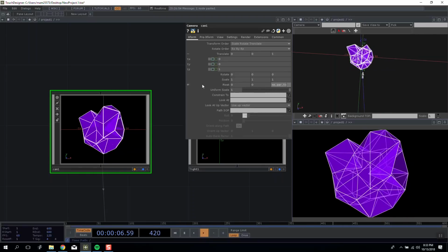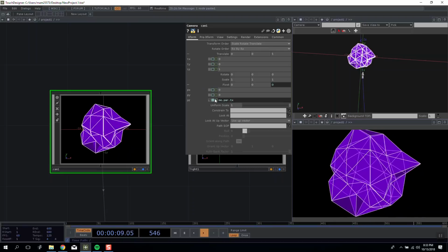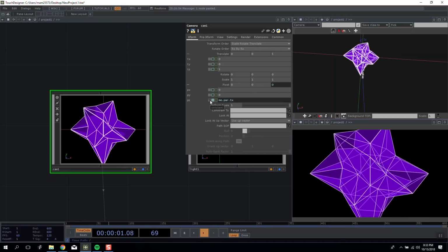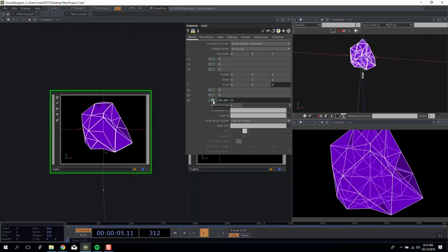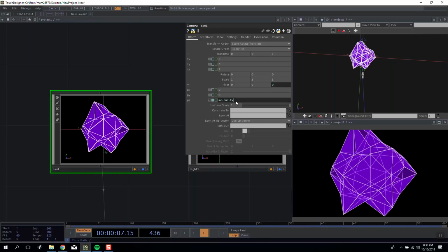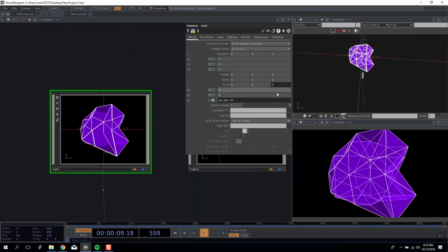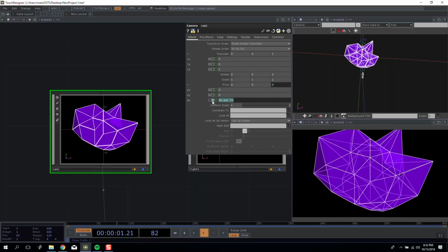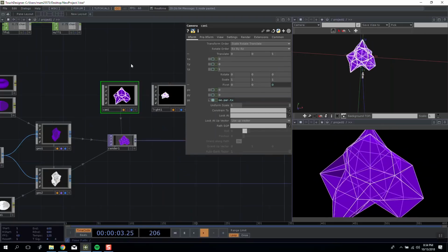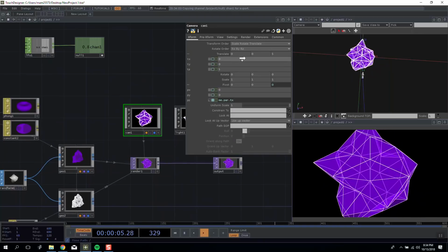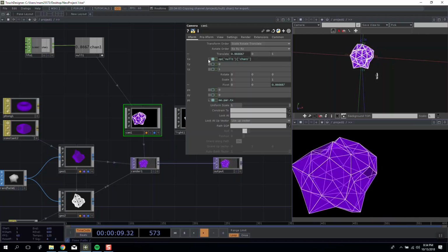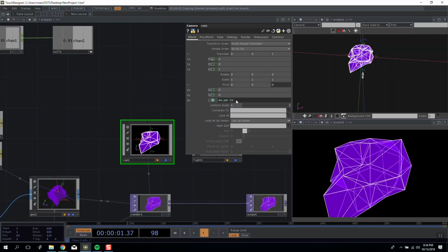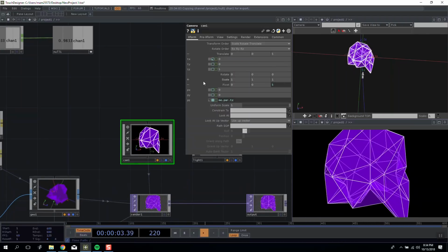If I now push enter and drop down this menu, you'll see that it changes from being the constant gray value to the expression blue one. So TouchDesigner automatically recognizes that I put a piece of code in there and goes and gets the reference. It's the same way that when we linked a chop, you can see that it turned blue and it gives us the reference. But I made the mistake and I typed tx when I actually wanted to type tz.